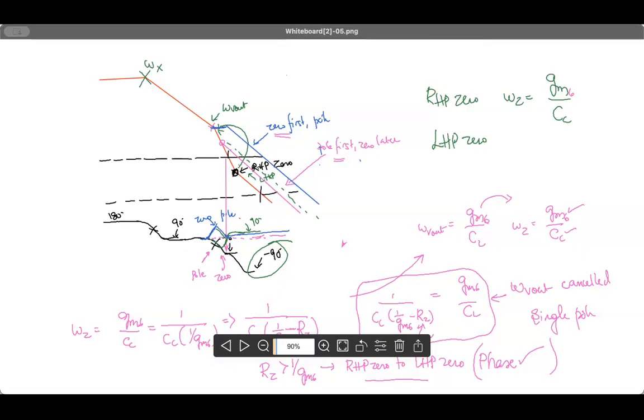So meaning whenever you cross the zero gain line, the black line, sorry, it's not UGB, it's a zero gain line. Okay. So whenever you cross the zero gain line, the 0 dB line, gain equal to 1, you see that your phase is already around 0 degree, meaning your phase margin is 0. You do not want to have that, and hence you would like to move your zero to the left half plane.